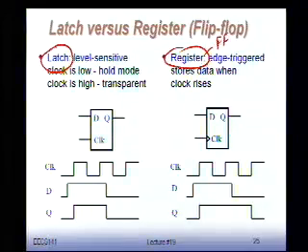Both of them are used interchangeably. Okay? So what's the difference between the two? Well, a latch is kind of a little gate. It's a device that has an input called D and an output called Q. Why D and Q? Nobody knows. The reasons are lost in history. But the output of a flip-flop is always called Q. Way back, somebody said Q sounds like a good letter, so let's pick Q, and since then it has always been Q. D is the data input. That I can understand. And you have a third input, which is the clock, something that provides that sequencing, that ordering effect that we talked about.